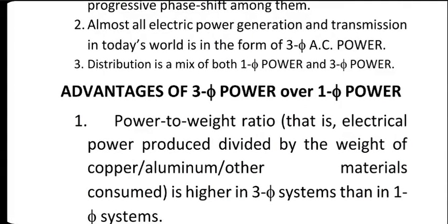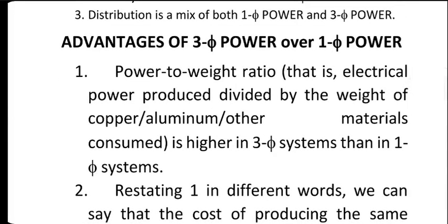Okay. So power to weight ratio, I'm not going to do theoretical calculations here, but it has been shown that it is much higher in case of a three-phase transmission. Actually, there is a formula which I don't have in this PPT, but there is a mathematical proof for this. But take it from me, that with the same amount of money, if you are building a three-phase system, you will be able to transmit a lot more power to society. That's one main reason why three-phase systems are preferred over single-phase systems, at least in generation and transmission.